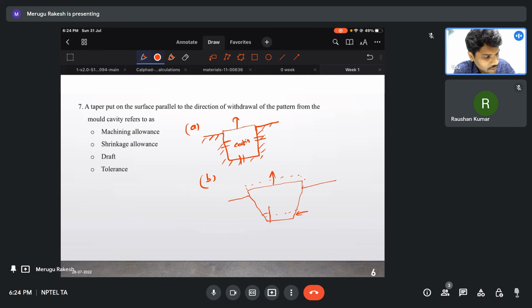This taper is very little, about 0.5 degree to 2 degrees. So it is a very small taper. It is like an understanding between the customer and the casting company. If the customer is okay with this small taper, it is fine. But if he does not need the taper, then finally we have to machine out this extra surface. But it is useful for us, even with some added, it will not damage the dimensionality.